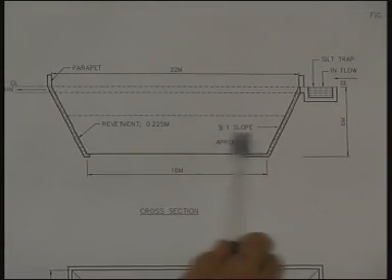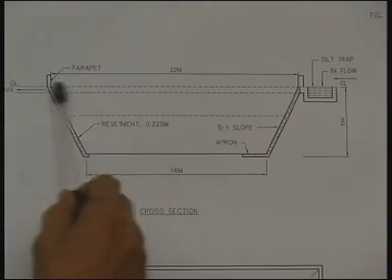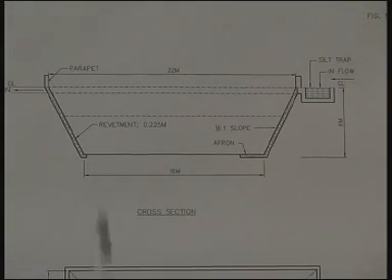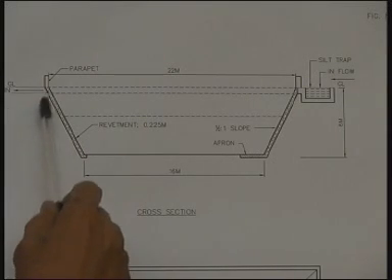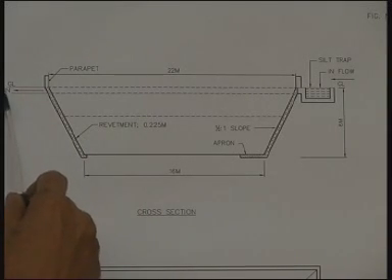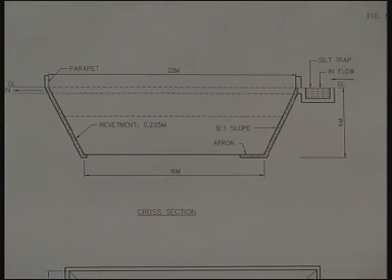Now as the water level rises, it will fill up this, and even this will get filled up at the time of very heavy rains, and an overflow has got to be provided. This overflow goes into a drain, and such drains collect in a natural wagu, a natural stream, and the natural stream can have a minor irrigation structure, a tank-like structure, which will in turn facilitate a recharge to the water table.